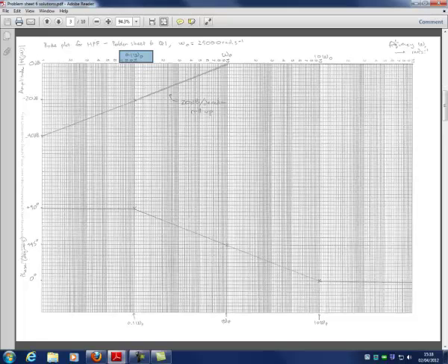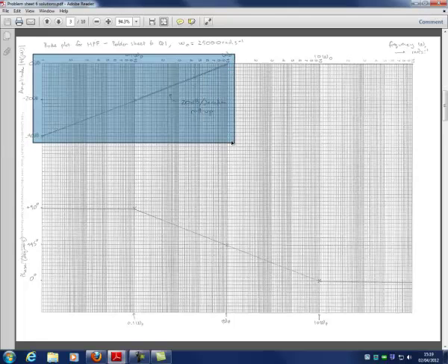And then I've labelled my axes, so that's the frequency which is increasing in this direction in radians per second, and I'm plotting the amplitude of H(j omega) on this scale here. So mark omega naught, which is here, and then the high frequency response is a straight line going all the way up to here. So it's passing high frequencies. That's what this means. What happens here in this section is where it gets interesting.